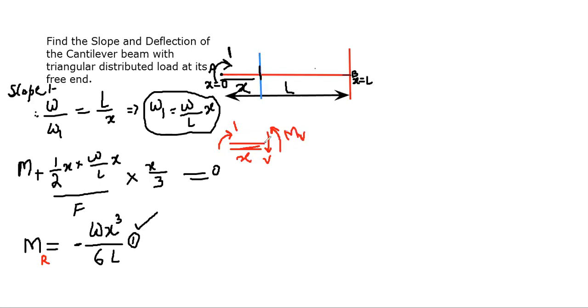Obtain this m_v by taking moments about an axis passing through the point where you have taken the section. First, you have this anti-clockwise moment, m virtual, m_v. And there is the 1 unit moment, which is clockwise, therefore we take it as minus 1 unit of moment. There is no other force or moment. Put that equal to 0. Therefore, the virtual moment becomes equal to 1 unit. Call this equation 2. We now have two equations: the real moment equation and the virtual moment equation.